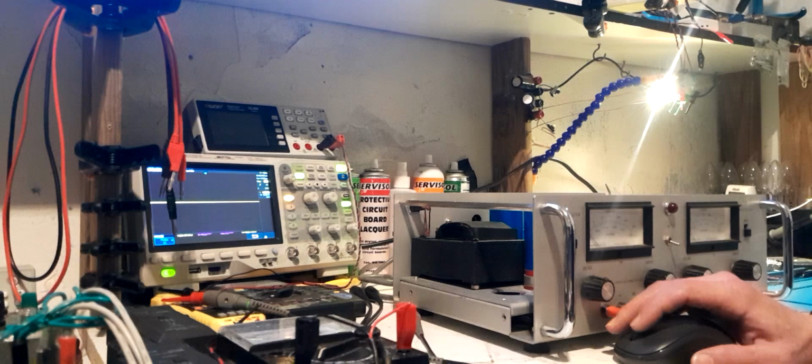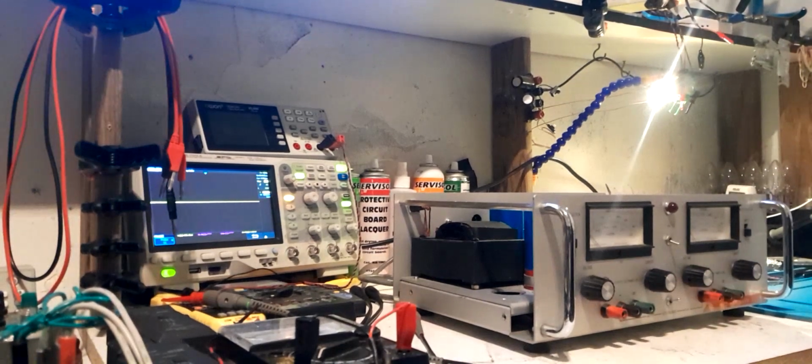Yes, 0.5% accuracy, and the cathode current minimum, IKA, is 35 microamps, and the reference pin current, IRF, is 150 nanoamps. Now, if we all remember the TL431B in the TO-92 package, minimum cathode current for regulation is 0.4 milliamps, and the reference input current is 2 to 4 microamps.